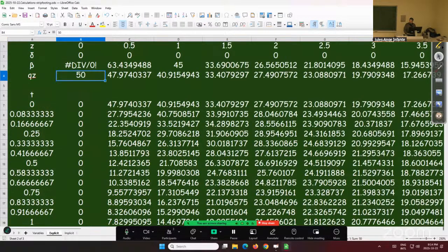Calculated, we find our total stress, or qz, that's our change in total stress, right? Caused by our loading. Then we said, well, at time zero, that's exactly the same, that's carried by the pore pressure. Because I put the load, instantaneously I say pore pressure carries the load. When you do an excavation, that's a negative load, so you have a decrease in excess pore pressure, which means that over time, water will migrate towards the excavation to compensate for that suction.